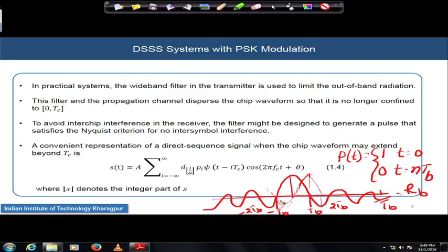So, if you design a pulse like this, it can be shown that you can transmit RB amount of data using a bandwidth. The theoretical minimum bandwidth required is equal to RB by 2 in such a situation. But it is really very hard to maintain the bandwidth within RB by 2. Usually we see that this first criterion, Nyquist first pulse design criterion, needs some excess bandwidth.